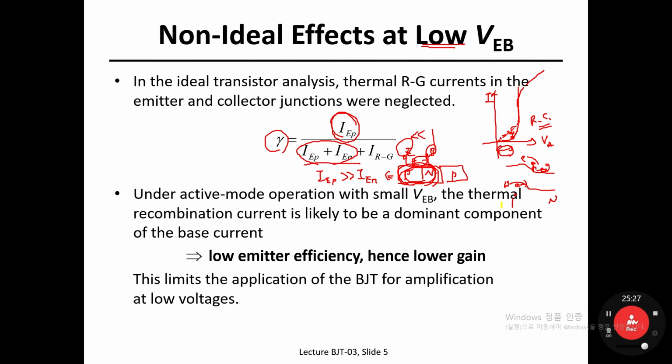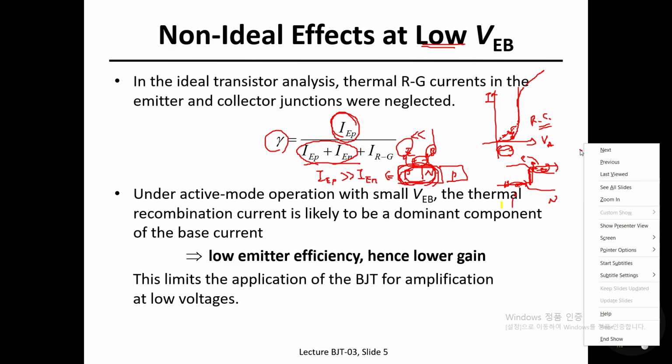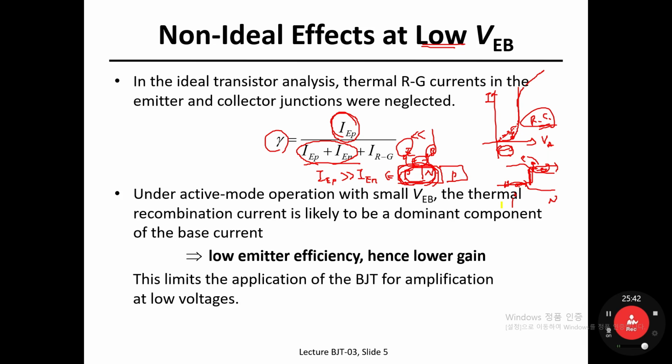However, once holes and electrons are recombined in the depletion layer, we may expect one more additional current path across the PN diode. That was the recombination current component measured in your PN diode at very small forward bias. The same event happens in your PNP BJT as well.